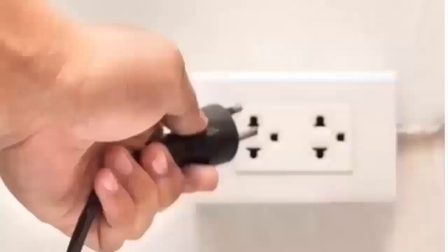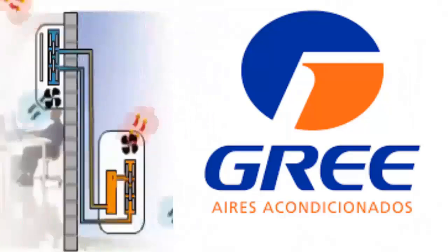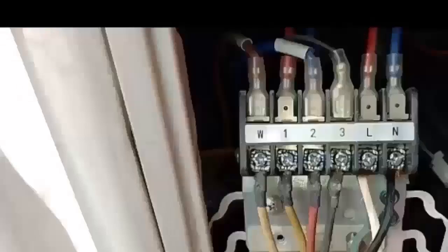1. Disconnect the equipment from the power supply for several minutes. 2. Reconnect the equipment and see if the error disappears. 3. If the error persists, check with a multimeter if the power supply voltage is normal. 4. A current consumption above normal can be related to electrical connection issues or loose contacts. You should check the condition of all cables.